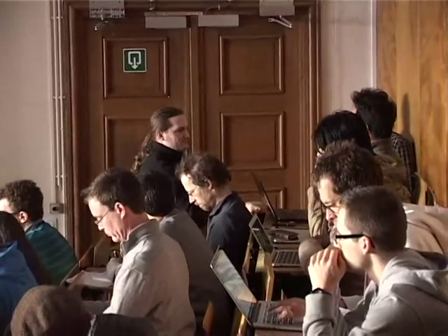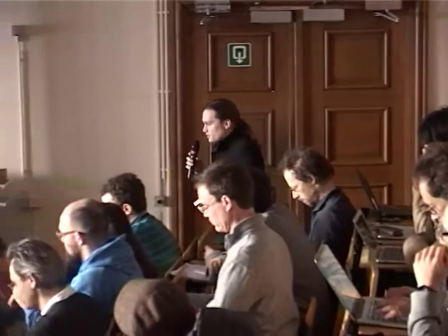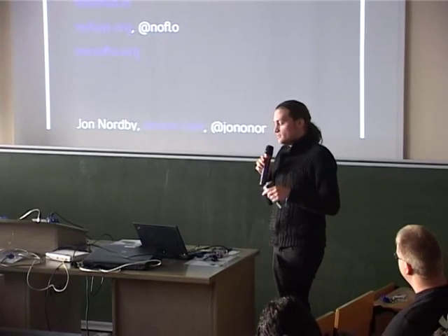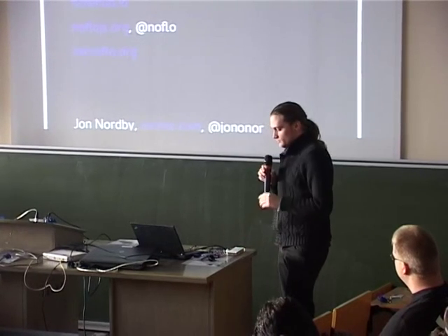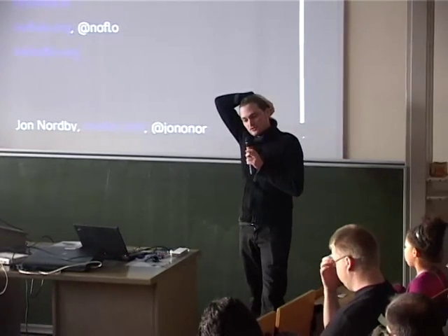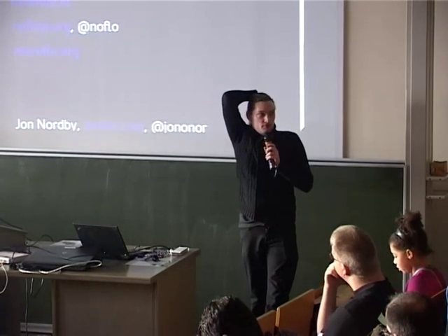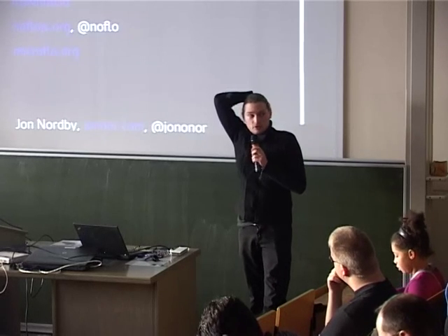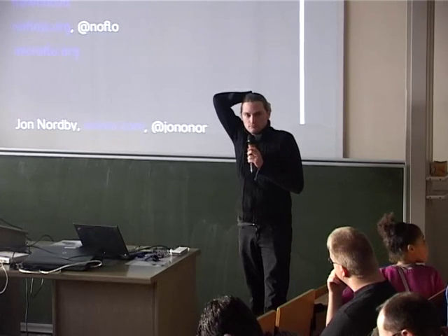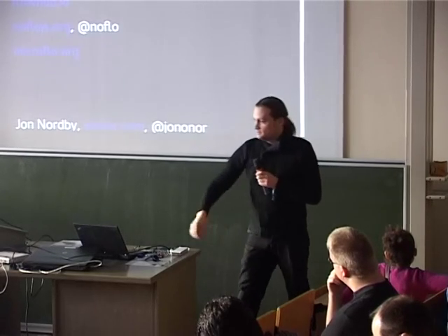Could you tell me the footprint of the current prototype on the microcontroller? So the current microcontroller here is an Arduino Nano, which is an Atmel ATmega328, the most common one. It's running with 500 bytes of SRAM and something like 16K of program memory for the standard image. It can run on ATtiny, which has a total of 700 bytes of SRAM or something like that. So it's pretty low.